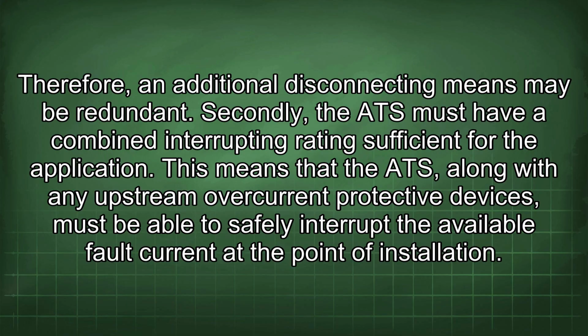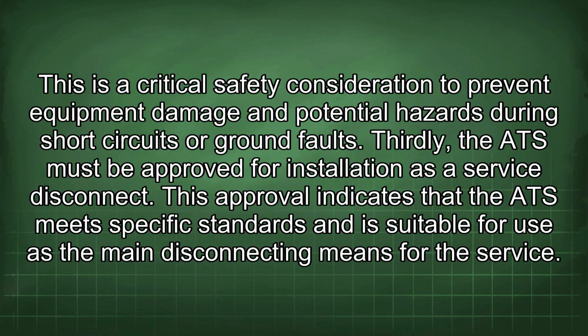Secondly, the ATS must have a combined interrupting rating sufficient for the application. This means that the ATS, along with any upstream overcurrent protective devices, must be able to safely interrupt the available fault current at the point of installation. This is a critical safety consideration to prevent equipment damage and potential hazards during short circuits or ground faults.